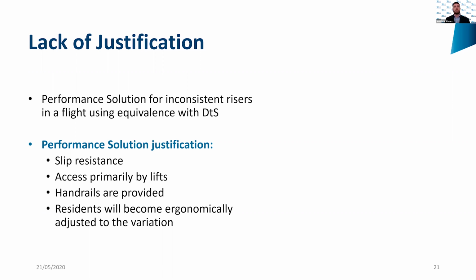There was a claim that the stairs had handrails. However, they're also required under the deemed to satisfy provisions. Now, if this was in a class 1 context, where the DTS only requires 1 handrail, there could have been the ability to establish what would happen if we considered the use of 2 handrails instead of 1. However, in this case, it was a commercial building and 2 were required under DTS.